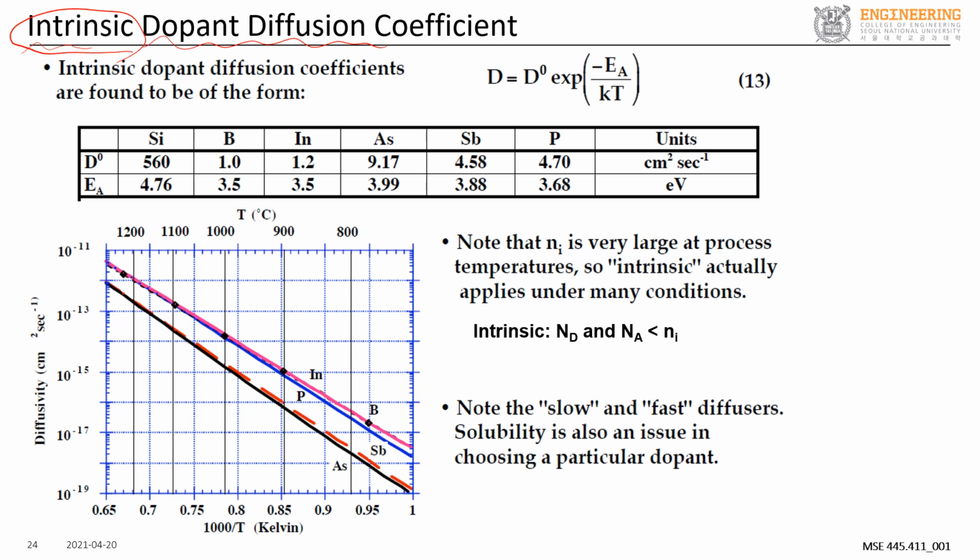It turns out if you measure, they follow Arrhenius behavior, just like any other process. So it depends on temperature a lot because it's an exponential function. You need to know the activation energy, EA. As a result, you can see that the diffusivity in the log scale will change a lot. This is almost a million times bigger as a function of different temperature.